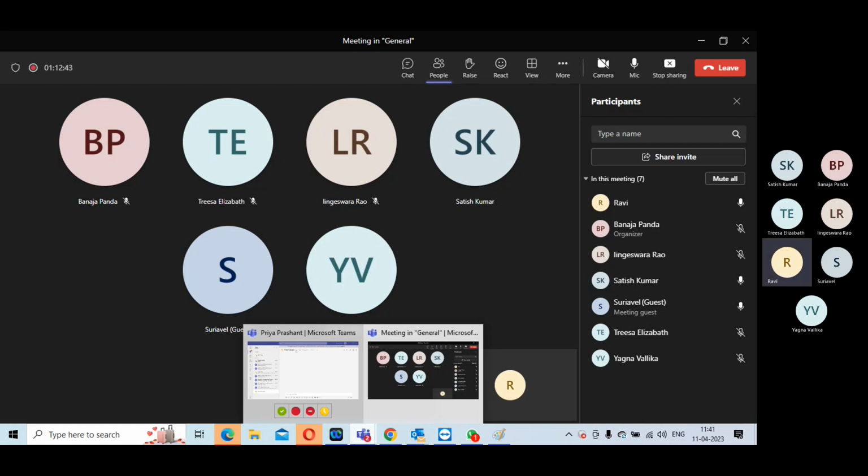Okay, so first, my data flow should be in sync with whatever the architecture requirement is, because of power domains and everything. Then you should answer questions in your interview like this. What is important? My data flow, my floor plan should match the data flow. My module placement should match the data flow, more or less. That's my first criterion. If that is done, then the second criterion for me is to address the condition.